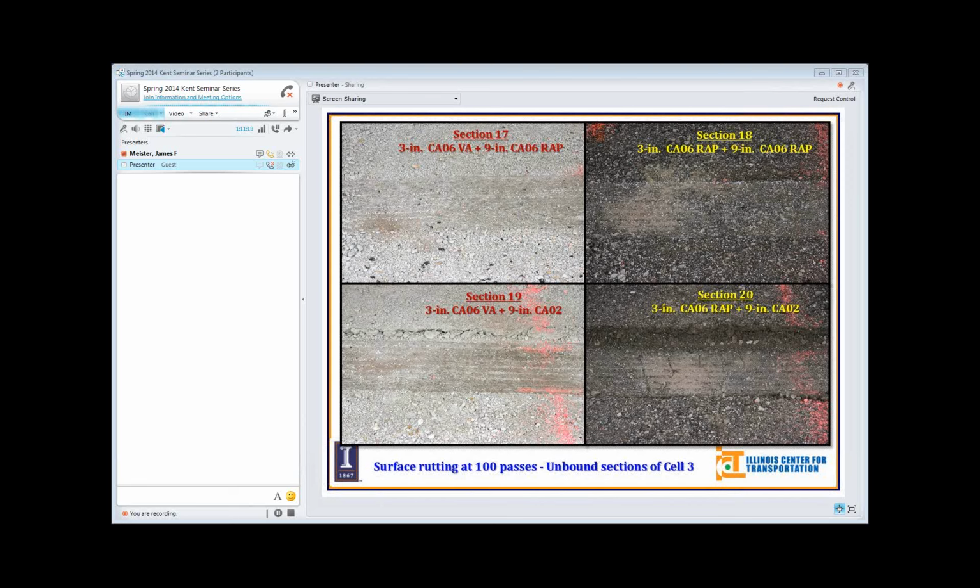So one thing we're comparing is how representative this is as a RAP, what you would put normally as an aggregate subgrade. That's something we're questioning now and further collecting data out in the field with the DCP. As well as, I think Hassan will mention, we will end up running this cell again, with tests conducted right next to this wheel path, the failed wheel path, to check if there is any effect of freeze-thaw cycles maybe.